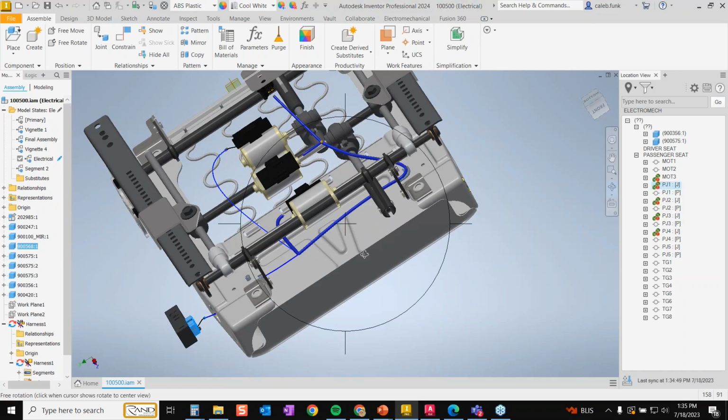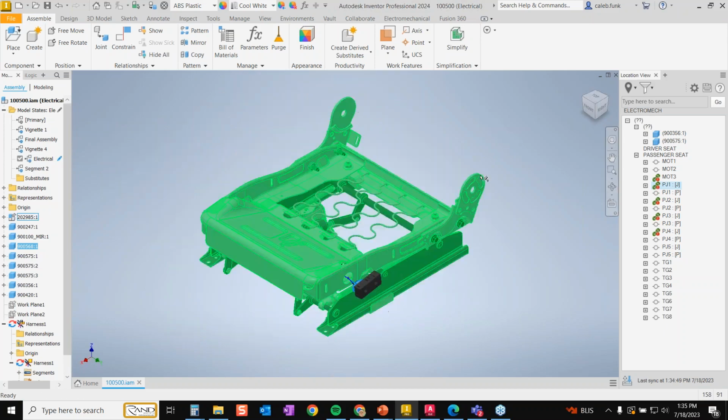So the idea now is that I could query this. I've got it built over here in 3D. I can check for interferences. I've got the same components listed in both locations. All of my bill of materials should match up. All of my naming should match up because I have the link between the two built within there. And that's what I wanted to be able to walk through today, showing the idea of creating that EMX file, having that build the connection between the different files, and then once that's built, have it manage the information between the different files.